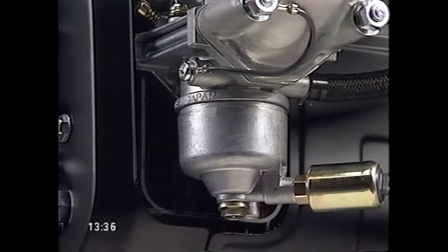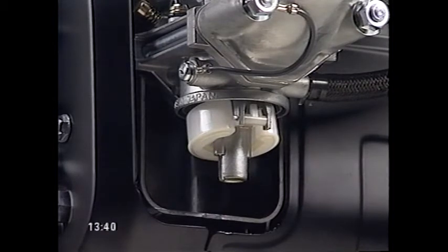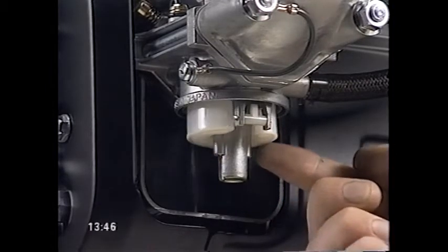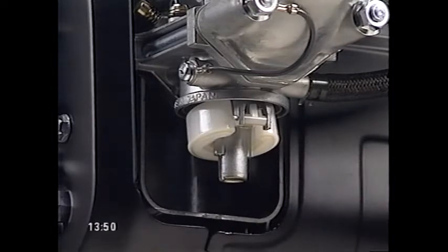The float name for the carburetor comes from the plastic float used to maintain the level of fuel in the float bowl at a more or less constant level. Proper operation of this float is critical, since atmospheric pressure on the fuel in the bowl, coupled with precise carburetor design, provide for transfer and atomization of fuel.